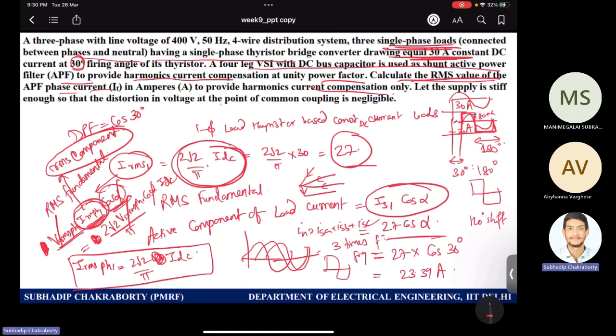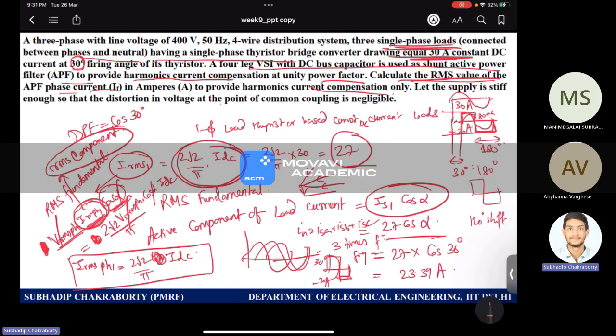So it will be toggling at a faster rate, but between the same plus 30 to minus 30. So please be careful that the sum of 120 degree shifted square waves is also a square wave, not like sine waves where it would be 0. What is the concept?